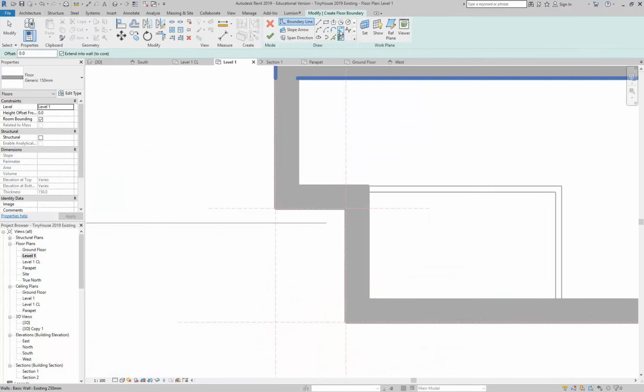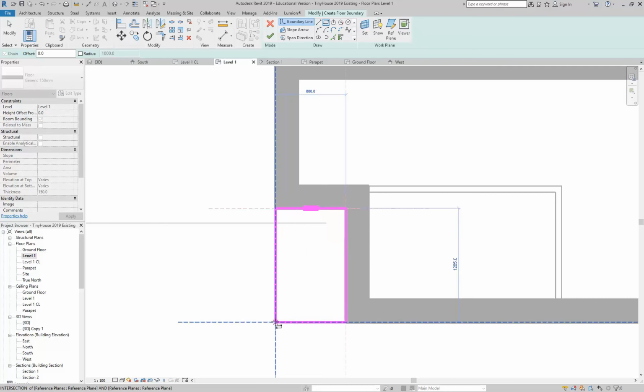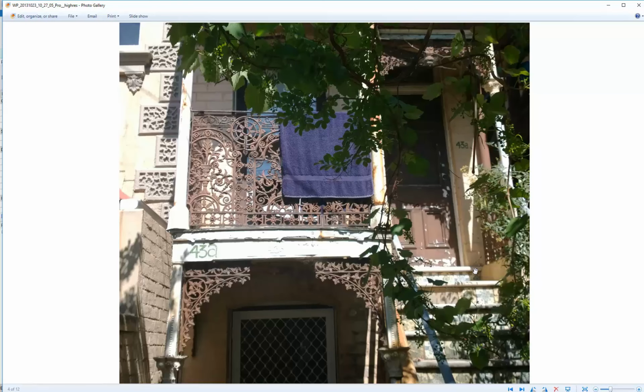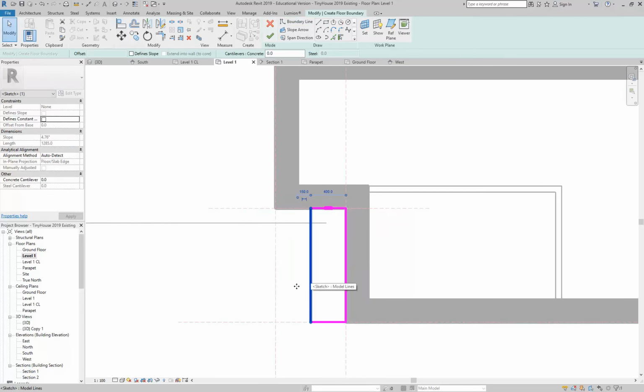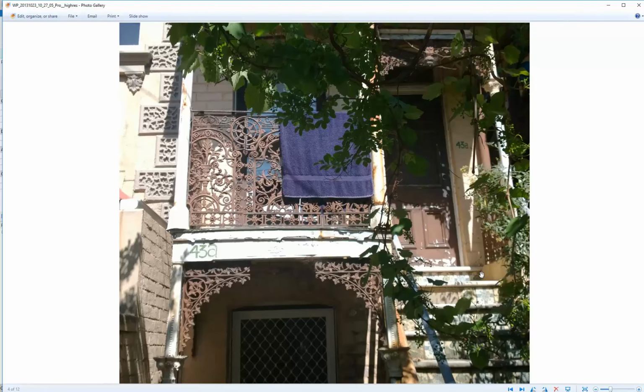so again, you've got the option to use pick walls, but always remember that you can just draw the shapes you need using the line tool, or in this case I'll use rectangle, and I'm just going to click in the corner there and then bring it out to here. That's roughly where it finishes, even though I think it's coming out a bit differently. Yeah, so actually the stairs go into there, we just got a little step, so that edge should be back about there. You know that that's not legal anymore, you can't do that now if you're following the BCA.